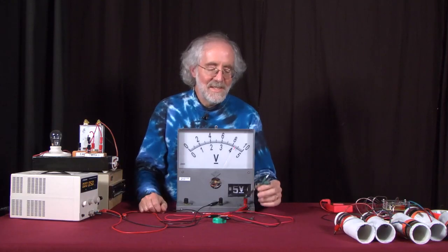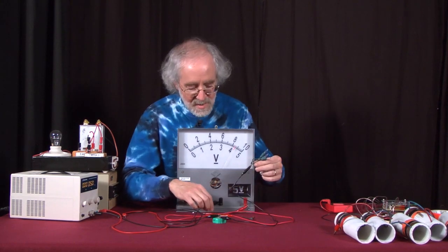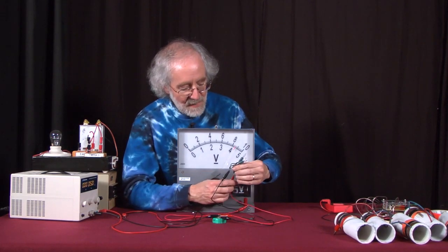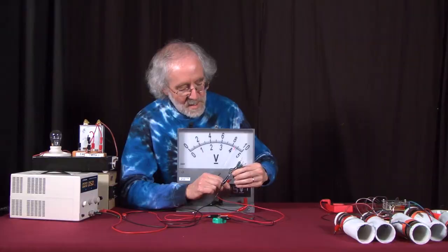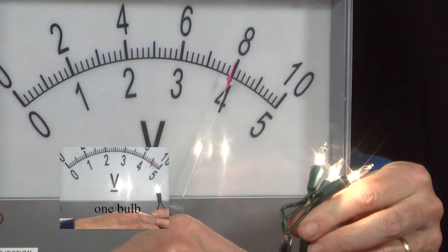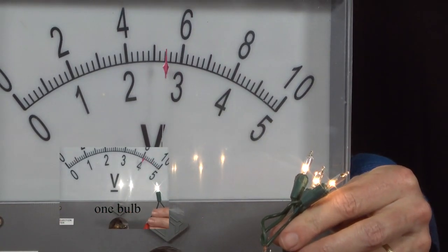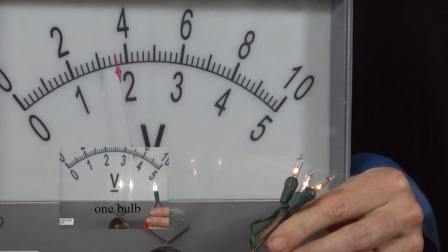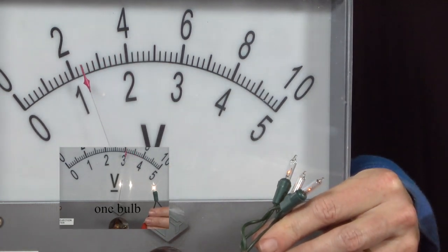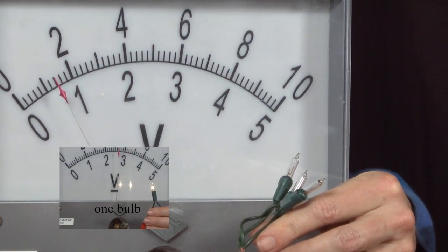Now think about this. I've got 3 light bulbs that draw more current, which means more charge flows out of the capacitor. And so if more charge flows out of the capacitor, what that means is it'll discharge more rapidly. And we can see that if I hook up these light bulbs. Watch the brightness decrease, watch the voltage decrease. And with 3 light bulbs, it drops much more rapidly, 2 to 1, much more quickly.